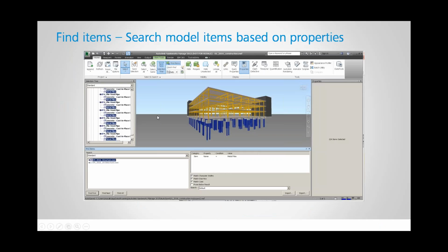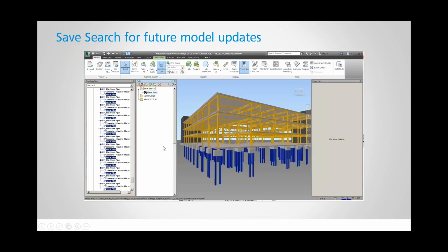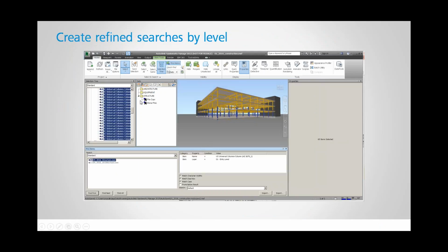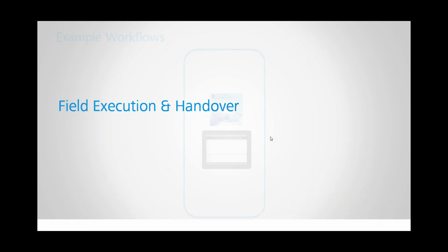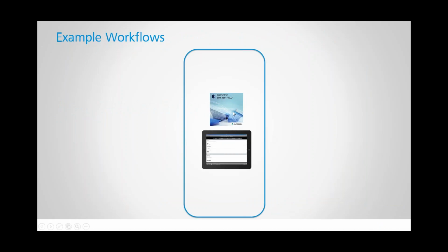We did go over this before with the search sets and then saving those search sets or saving the equipment sets, etc. And what I want to move into now is the handover. So during any project, things always change on site. There's always going to be requests for information. There's always going to be maybe a door change if it's a project that takes place over a long time. Building codes could change. So maybe a fire-rated door could go from being a 60 to a 30, require a different type of hardware treatment.